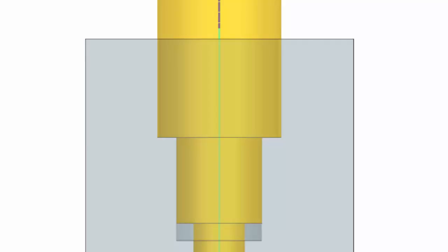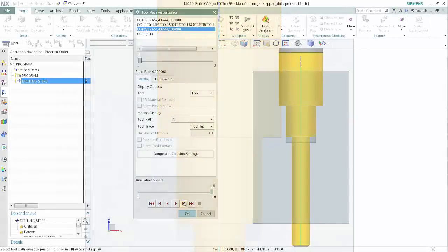This is an explicit action to drive a particular tracking point to a particular depth and is therefore seen as an intentional gouge. This behavior is desirable when holes are modeled slightly undersized but the user still wants to cut the diameter with a larger size tool, or it results in a depth slightly deeper than the modeled depth. Click Cancel.